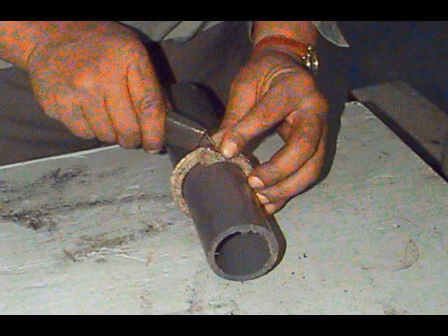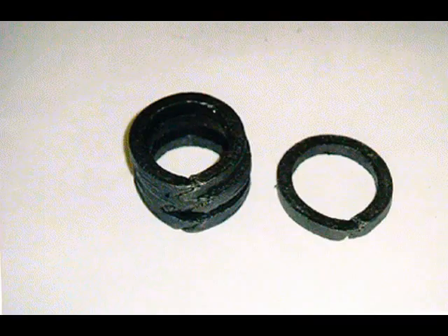If there is no shaft wear, rings can be cut on the shaft outside the stuffing box if there is room. The packing should never be laid out straight on a board and cut. This will result in a joint that will not seal. Each ring can be cut in the same manner, or the first ring can be used as a master from which the balance of the rings are cut.